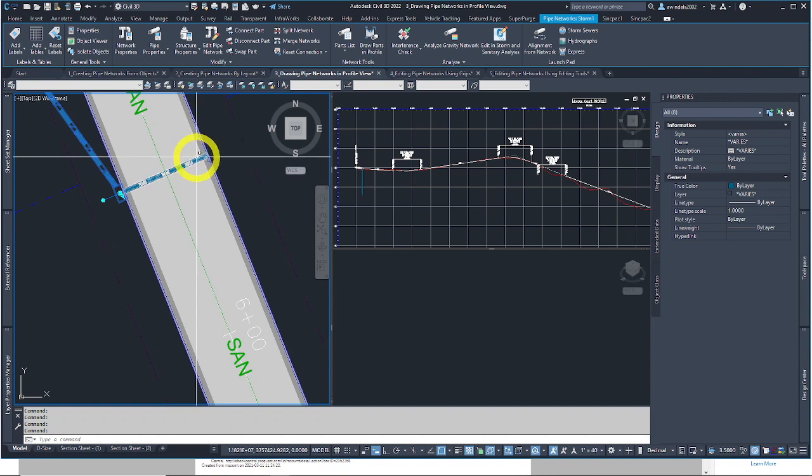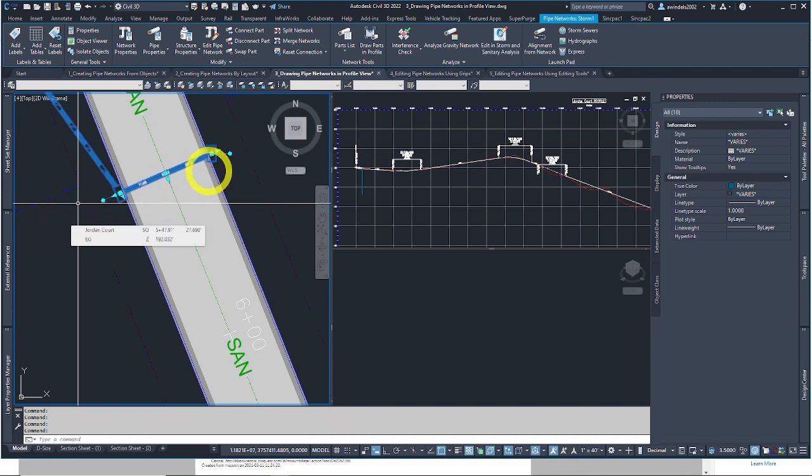And some of these are going to look kind of weird because of these parts and pipes and structures we're picking, we apply them to this profile view. This profile view follows along the center line of this alignment, keep in mind. So when we superimpose these structures and pipes, they're with respect to the alignment. So these ones here at the end are going to show as a little bit of a blob. They're perpendicular like this, so it's just going to be one structure. We'll see here in a second.